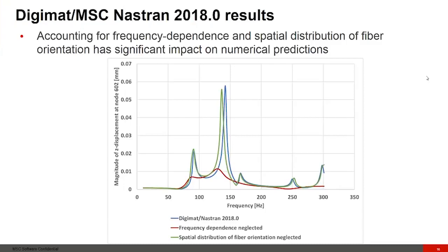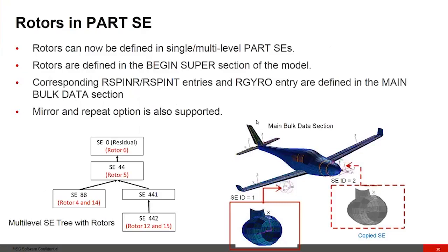So this is just an example output where we're showing how well MSC Nastran can track the modes. Some of the limitations of eigenvector-based mode tracking: it can only be used with the HESS option, and it's for analysis in a fixed reference frame only.